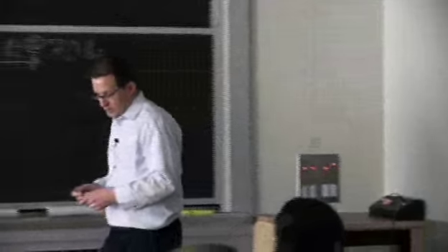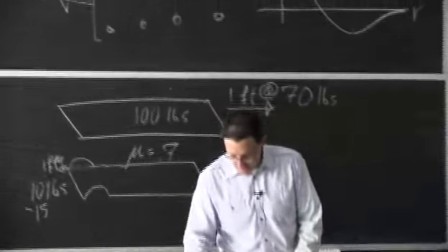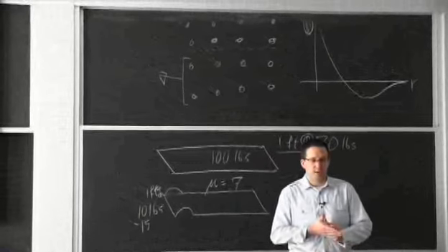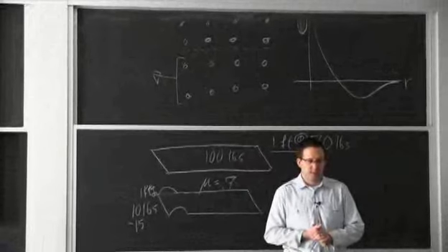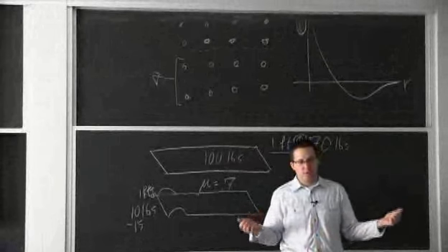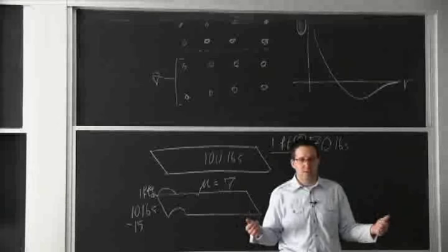And one thing you'll see is they don't have the same length. Also look in the center, some of them, especially the 600, really have an orange peel type of effect on the surface. That has to do with the grains, and we'll talk about that. But just take the time it takes to circulate them, so when we're at that point, everybody already had a chance to see what the samples look like. The one that stretched the most is the one that was heated to the highest temperature.